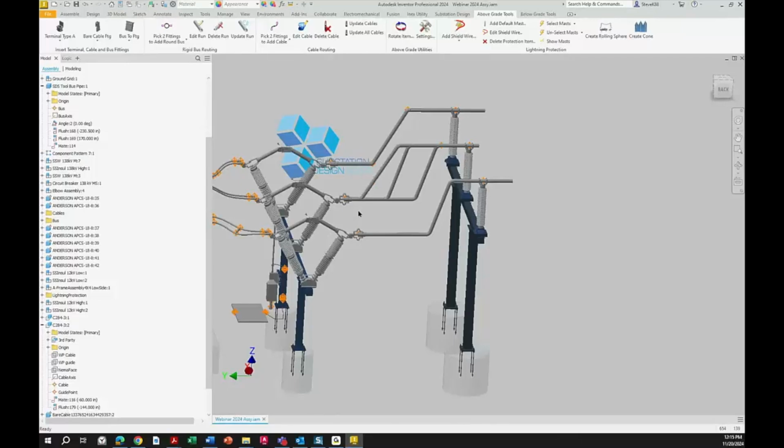And you see another location of where it's being placed. So depending on the direction of pick, it's going to show you where it's bending. So I'm bending either from that fitting to this fitting, either with that work point, which is the center one, or without the work points, it gives me this one. So by having this pipe tool in here, this SDS bus tool in there, I can adjust where I want that bend, right? So I can be more precise on my bend location.